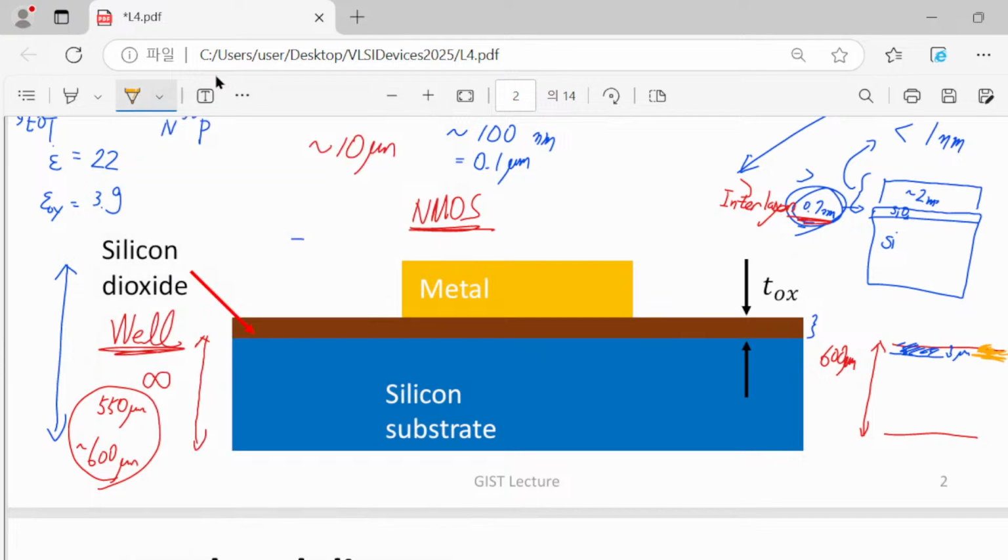N-type dopant should be introduced, and at the same time, the thickness of this so-called N well is at most just micrometer thick. So are you with me? So if we just draw the scaled version of this structure, actually you cannot see the thickness of these wells. These wells are extremely thin compared with this entire one. So think about 600, and in this 600 you have to recognize just one or two. If you draw it, then how does it look like?